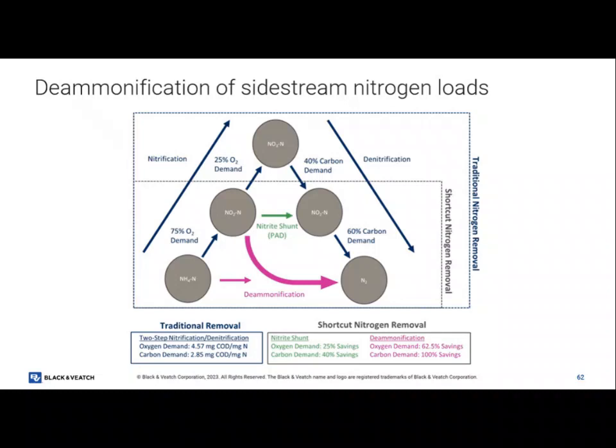So when we think through this, I'll draw this graph first. This is F to M, grams of SCOD per gram of VSS, and this is granule size. Essentially, our F to M is grams of soluble COD. What's really impacting our granule growth is our VFAs and that readily biodegradable COD. And so when we start talking about that, we have this F to M gradient curve.